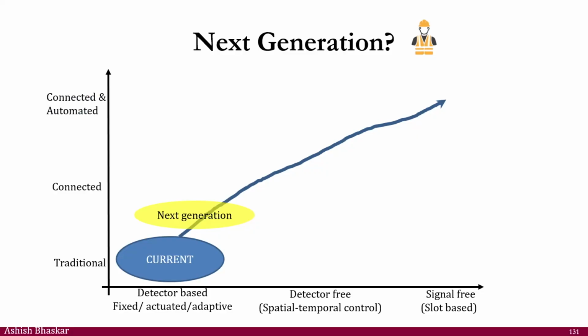Generally it is a corridor, for example, one well connected towards a CBD, a central business district, or some other area, or let us say an airport. I know a high volume is going in this direction, so it is better to just flush the high volume. You can even think of another way, hold and flush: hold them upstream first and then flush them. You can let them queue there, but then you can flush them.